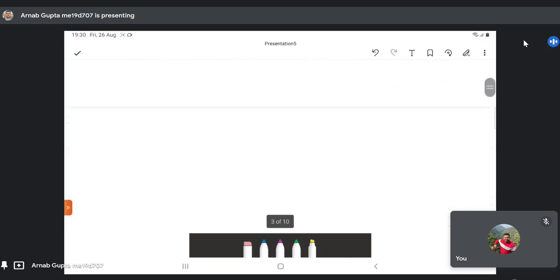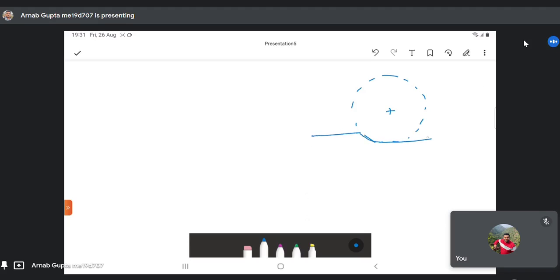And in cases of down milling, what happens? In cases of down milling, you have your tool here. This is the workpiece. So say your workpiece is being fed in this particular direction by Vf. This is the depth of cut, δ. Here, the milling cutter will engage the workpiece in this manner. So this is one of the teeth that I am showing.